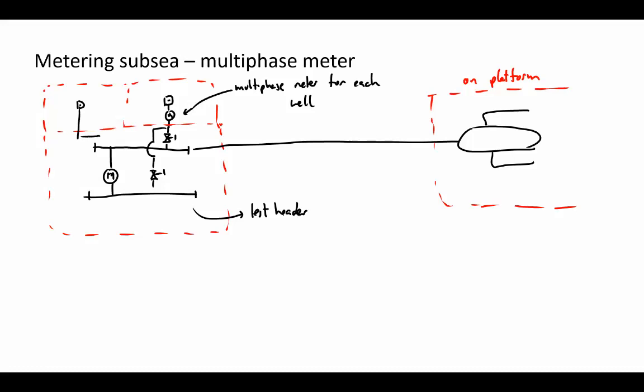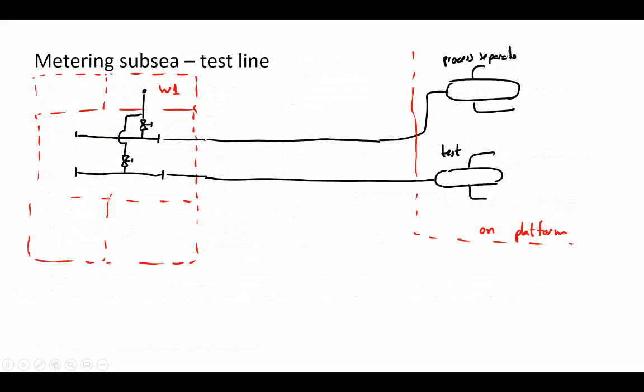So you have the option to go either to this header, or to this header, from well 2, if you have one common meter for all the wells. Then you decide if the well is simply producing, or if not, I put it to the test header, then it flows from the test header to the production header, and then you can measure how much each is producing. And in this arrangement, you can use a common meter for all manifold wells.